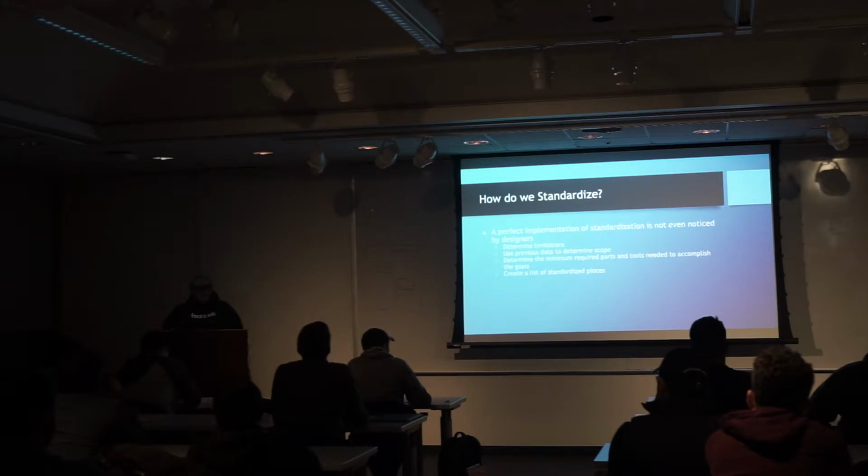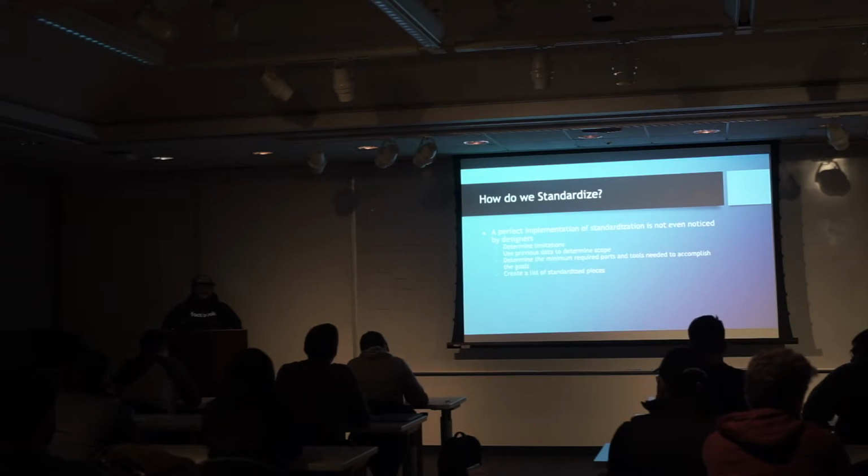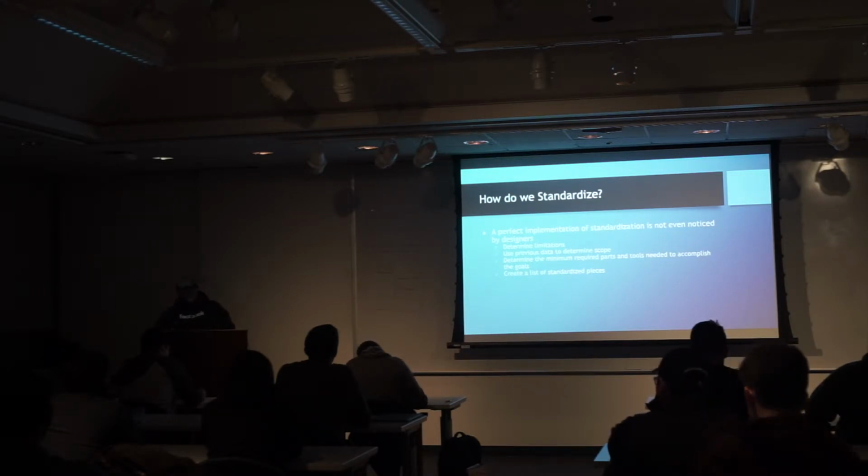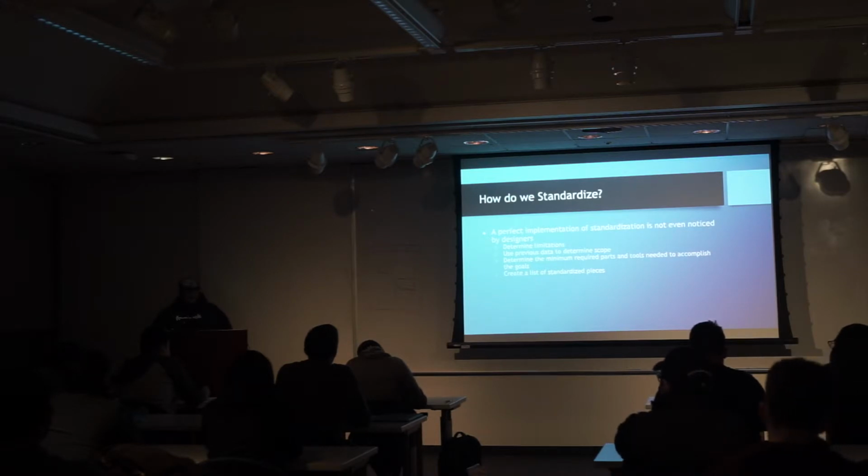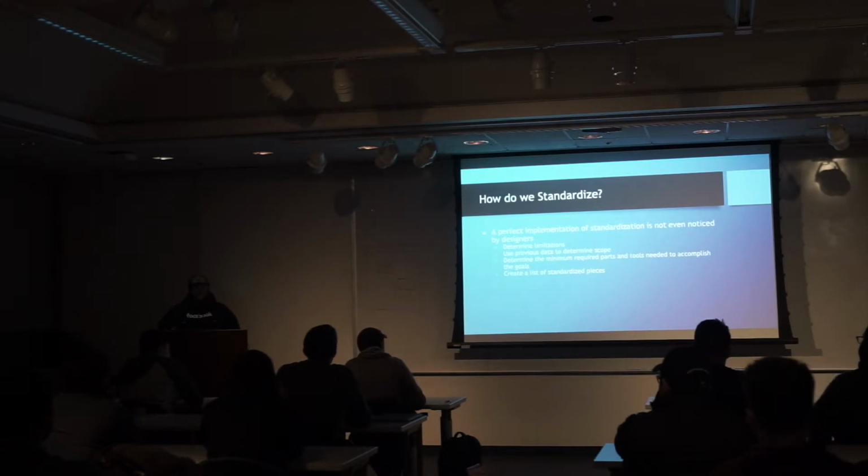So there are obviously going to be limitations, but what this says is you want to use some sort of data to determine your standardization, right? You don't want to just say, oh yeah, we're going to use 5/16 bolts for everything out of nowhere. Because if you look at the previous cars we've built, a lot of people were using 1/4-20, right? So that's data you can look at. You can go look at parts we've made, parts we've designed, and use those to determine where most, like your 90%, is going to be.